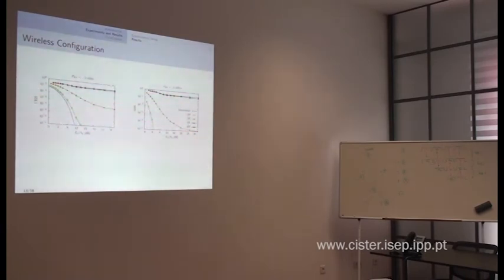So this again is chip error rate. These are symbol error rates. It's slightly different because this is after you use some coding embedded into modulation to fight the multipath problem, and that's called direct sequence spread spectrum. Basically you use that demodulator on top of the other one and recover the symbols, and that should give you a better error rate than if you don't use it. What you sacrifice is data rate. You have a lower data rate.